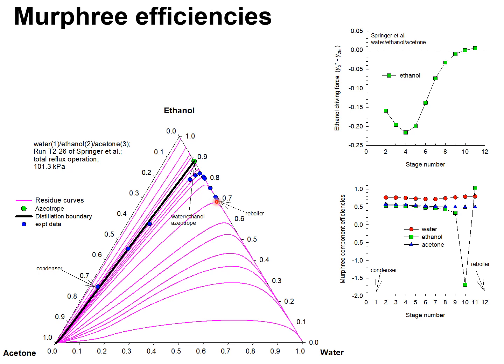The experimentally determined composition trajectories are shown by these blue circles. And the first thing to note is that this is the reboiler composition, and this is the condenser composition, but the condenser composition is on the left of the distillation boundary. So the boundary has been crossed in this set of experiments.